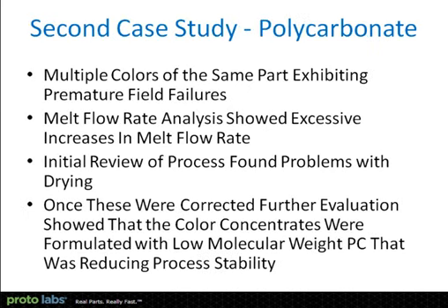Here's a second case study. This is also polycarbonate. We were looking at melt flow rates that were excessive in the molded parts. The way this first showed up is parts that are warranted to last a minimum 3 years are cracking in the field in a period of anywhere from 3 to 6 months.